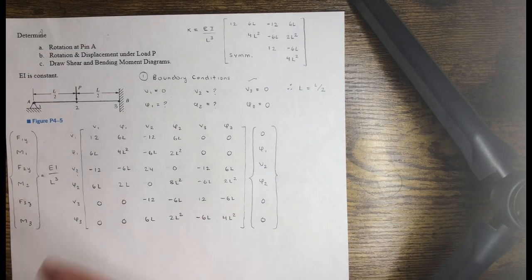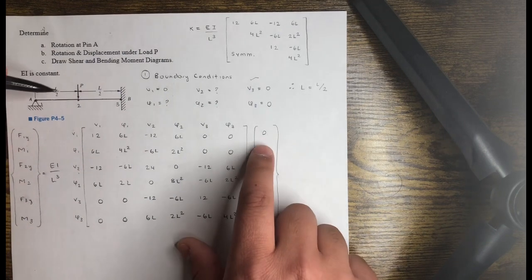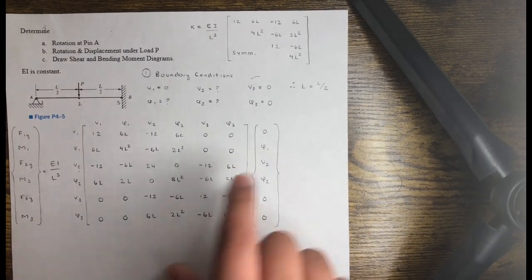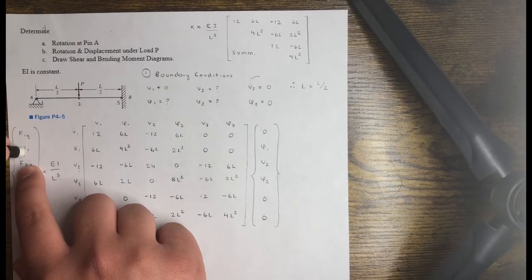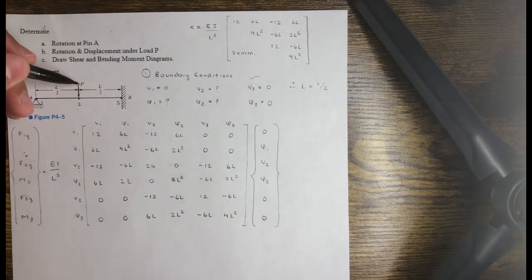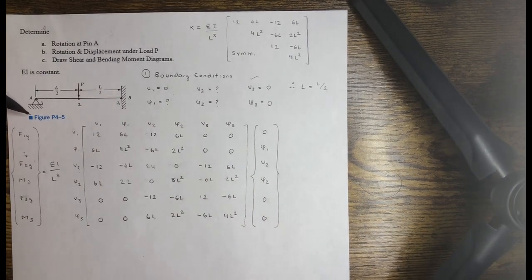So just by observation, we see that at pin A there is going to be a force, because it's displacing, so we don't know it. We don't know this one, so we should know this one. It should be 0, it's a pin. It's going to rotate however you apply it. If you put a force here and you're applying it upwards, it just moves up. That's all it's saying. There's no reaction for moment there.